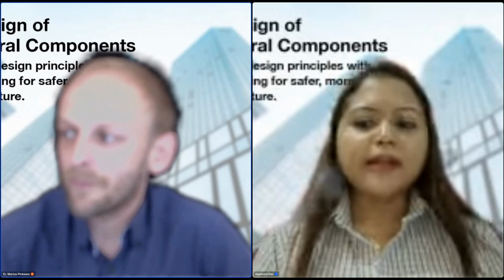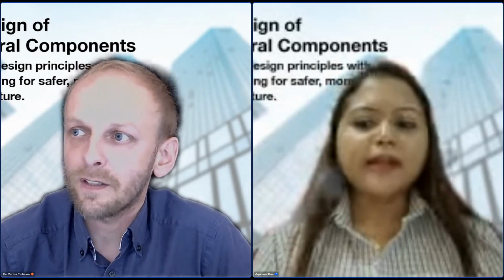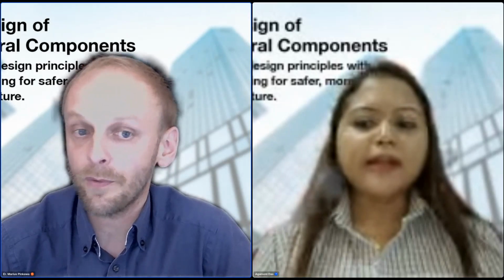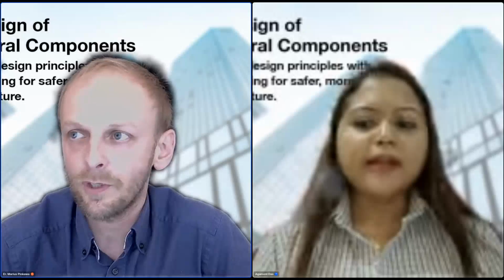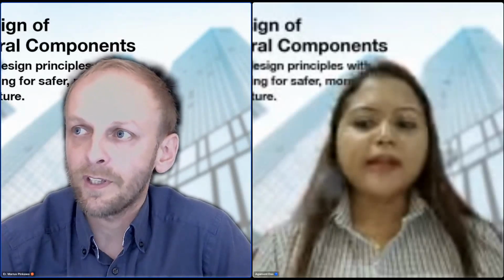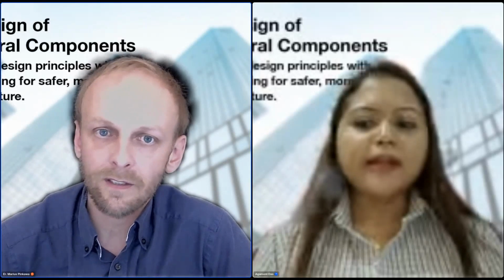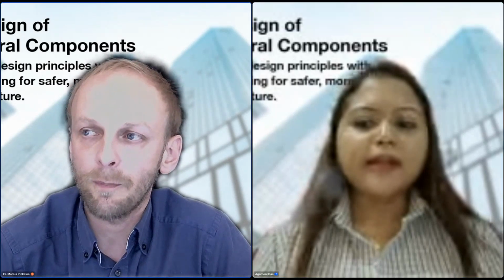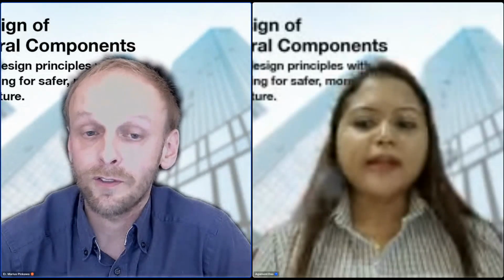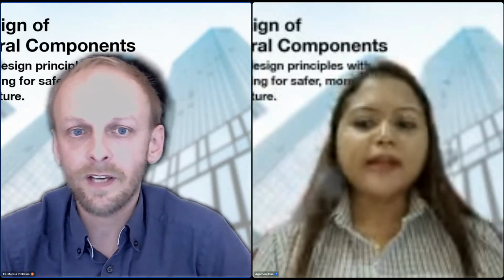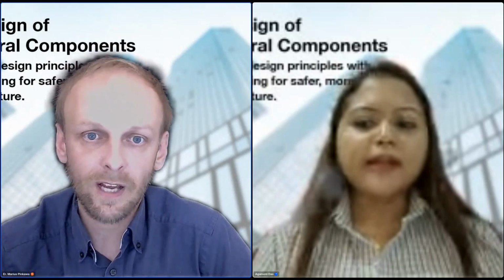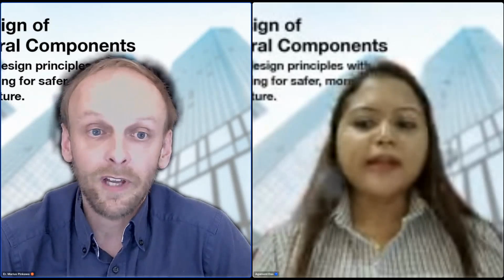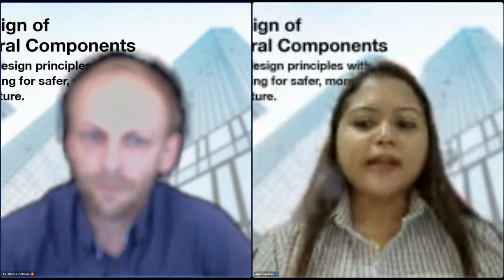Okay, so basically, if these are closely spaced modes or periods, in the simplified formula you have Ta to T1, the dynamic amplification factor. In Eurocode 8, in the simplified formula, the amplification factor will be very large. If you have just the table values, like in the Indian seismic code, you have to choose the largest possible amplification factor. If you calculate floor response spectra, you will see a very large peak.